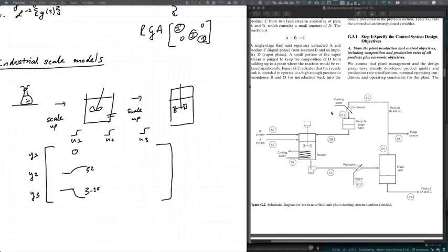And then in terms of choosing manipulated variables, so that was choosing controlled variables, right? But then there's choosing manipulated variables. And again, we think about that from availability of the degrees of freedom on the flow sheet like this. But we can also think of it in terms of cost, because adding a valve that is a control valve in over here, process designers are always at odds with process control engineers, because control engineers want to put in very effective valves.